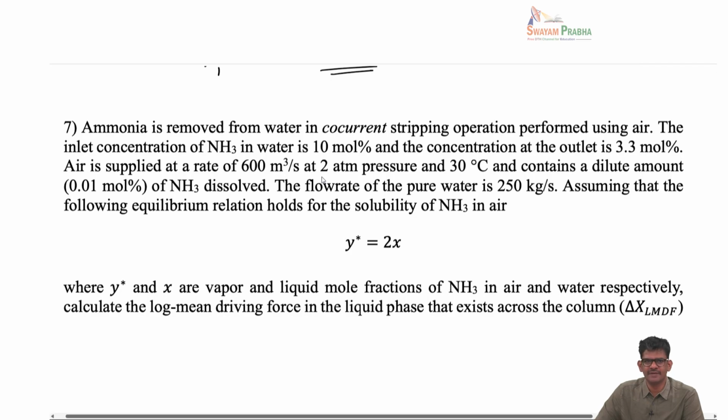It illustrates the driving force calculation that we generally do in heat transfer. In heat transfer, we calculate the log mean temperature difference for co-current and counter current. In the same way, in one of the classes I mentioned the analogy between heat transfer and mass transfer with regard to the average driving force. In co-current, there will be a large mass transfer driving force in the beginning, and then it will diminish towards the other side.